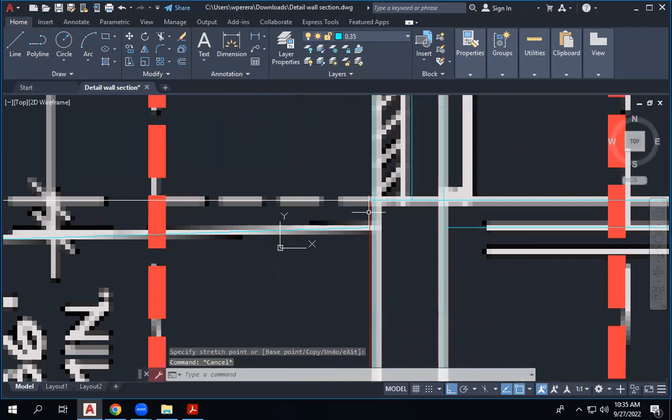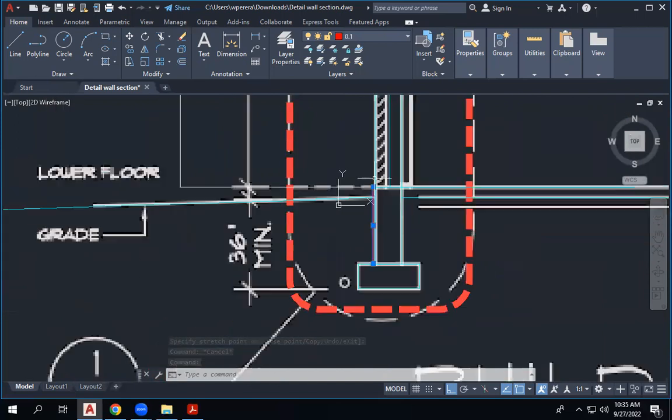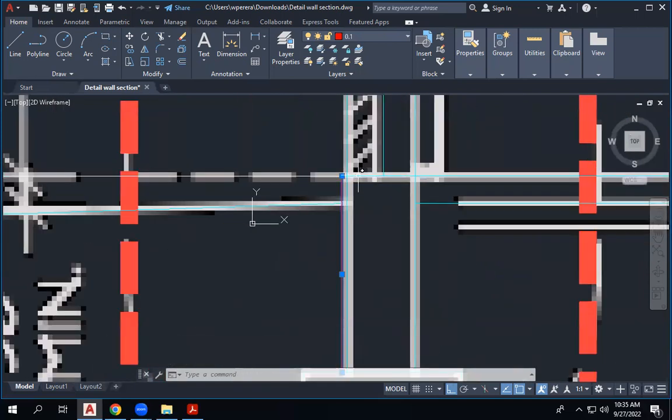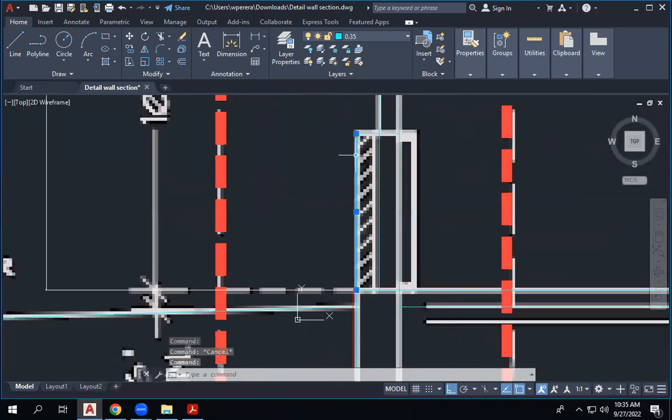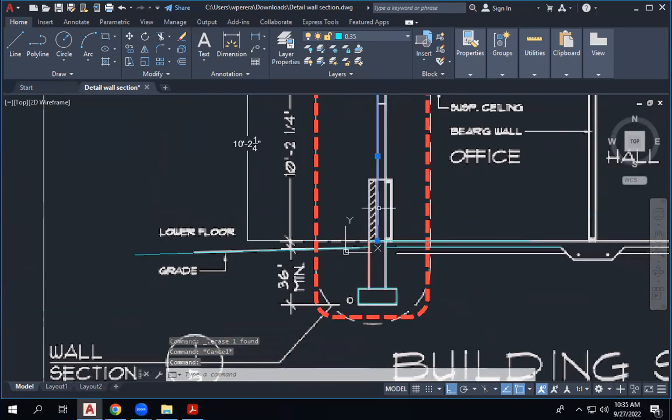But now we need to have this vapor barrier right up to the top of the foundation. That's essential. So it would even go past the ground. Past the ground, yes. Now we will remove this line. We will not have it. Just these two lines. You draw these two lines.